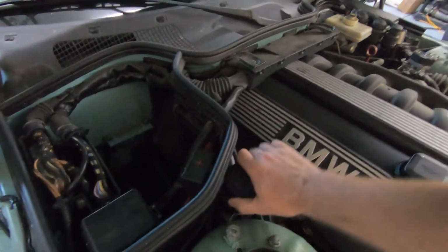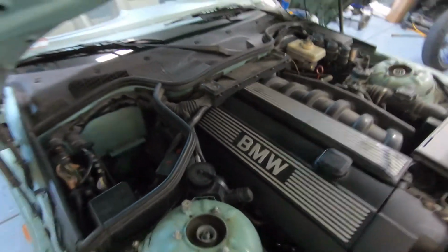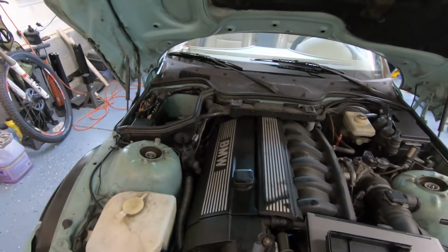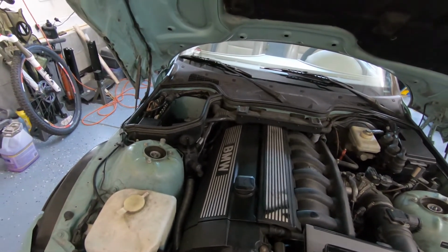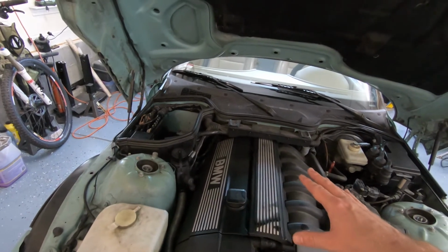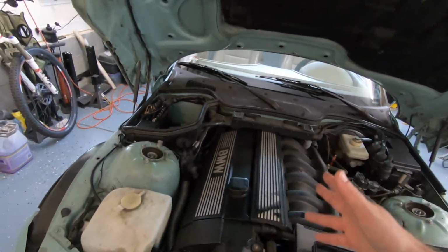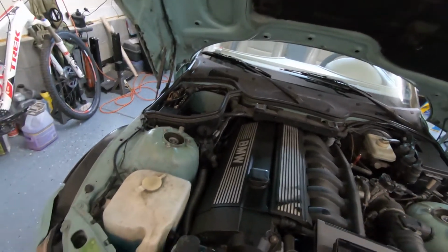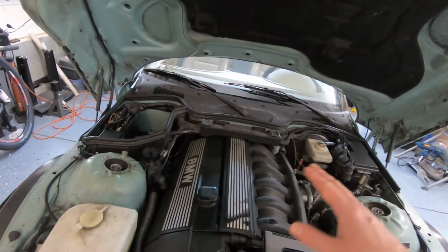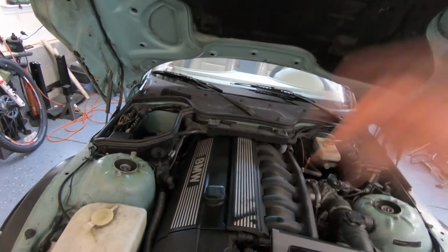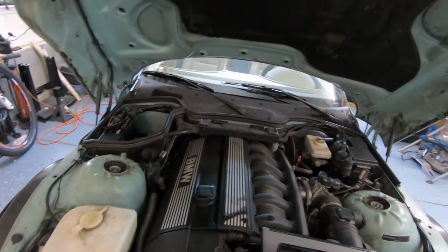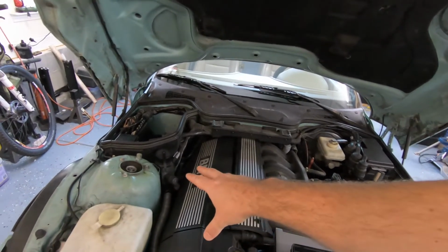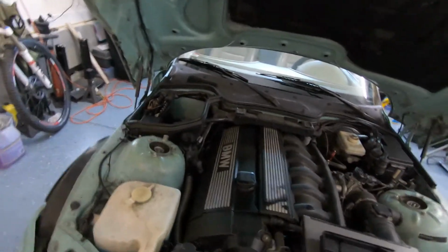Now, these vehicles connect all their control modules via something called CAN bus, and there are different iterations of CAN bus technology in terms of the protocols used. Early on it was called L line. After that I think it was K line, and now there's D line. Those are the options of protocols and interfaces you need to interface with your car. For this Z3, it seems that I can access all the control modules through the 20-pin connector.